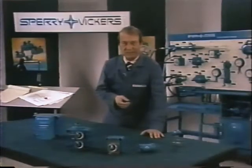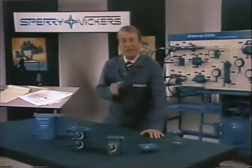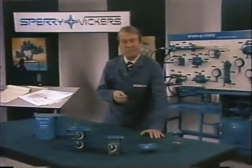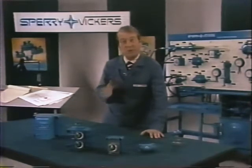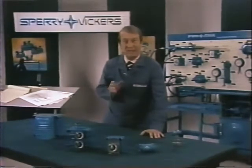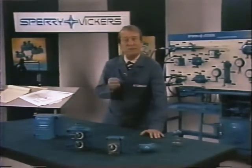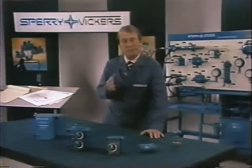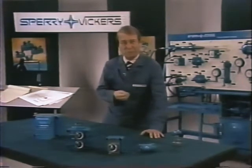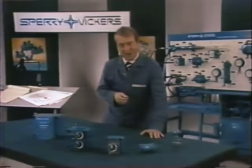Just to recap a little bit, we have the meter-in circuit where we have the flow control measuring the oil into the work cylinder. If we had an overrunning load condition, we could put the flow control on the exhaust side of the cylinder to restrict the flow coming out. And we have a meter-out circuit. If our speed requirements don't have to be too exact, we can take advantage of horsepower savings and use the bleed-off circuit where the excess flow goes to tank through the flow control rather than over the relief valve.